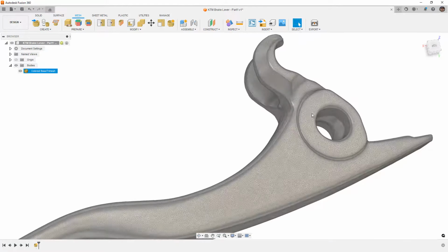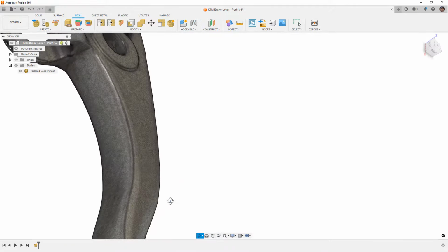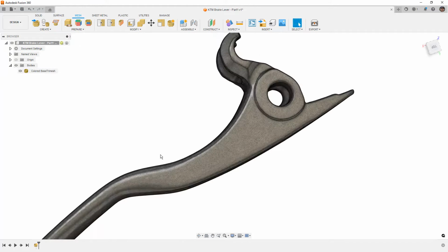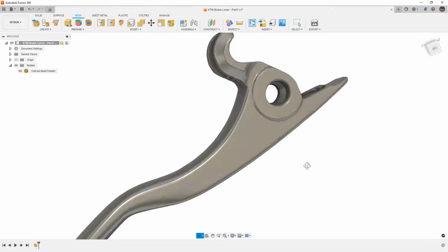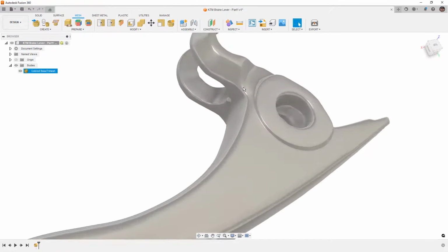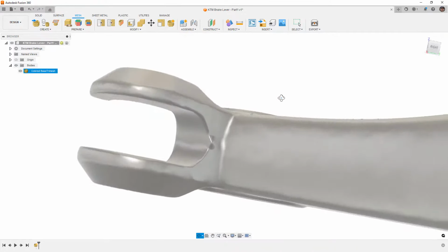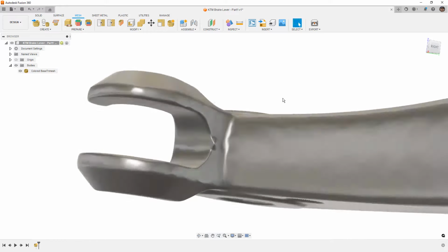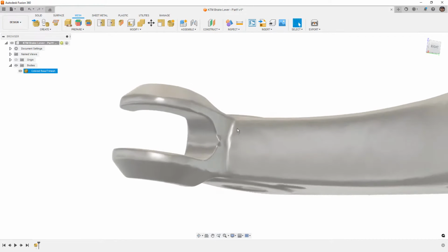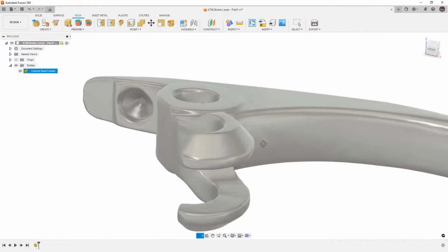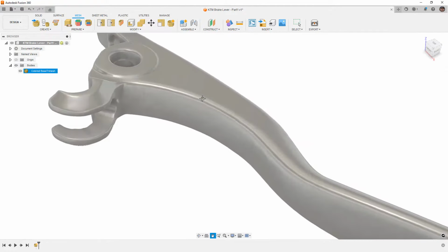And by the look of it, that fillet carries onto this edge and carries down. Maybe it increases in size, but for the most part, that is a consistent radius. I do Control and 4 to hide the edges. So I would need to pay a lot of attention to where these edges are and how all these edges are coming together in order to create that fillet. Again, this is a cast part and there are imperfections in it. So we're going to have to make some concessions about what we want to see here. But, overall, those are the things that I'm looking at.